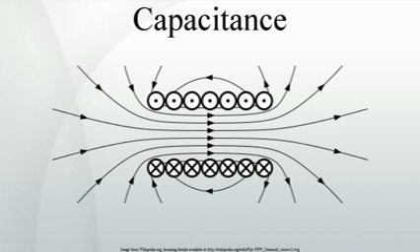Single electron devices. The capacitance of a connected, or closed, single electron device is twice the capacitance of an unconnected, or open, single electron device. This fact may be traced more fundamentally to the energy stored in the single electron device, whose direct polarization interaction energy may be equally divided into the interaction of the electron with the polarized charge on the device itself due to the presence of the electron, and the amount of potential energy required to form the polarized charge on the device, the interaction of charges in the device's dielectric material with the potential due to the electron.